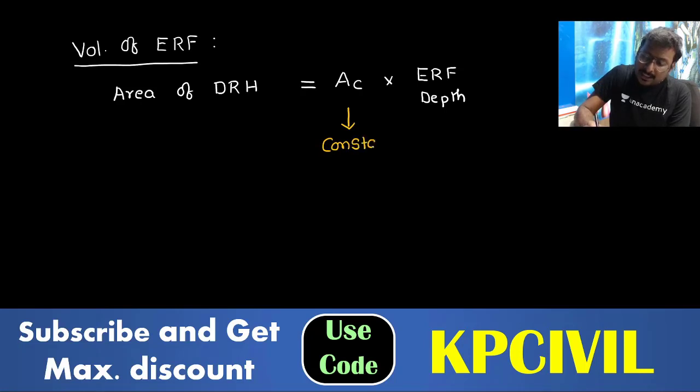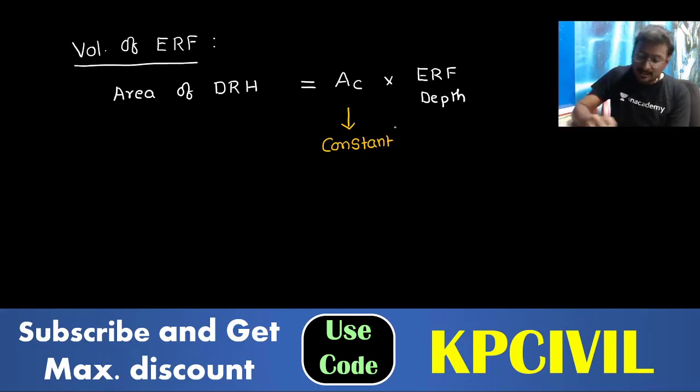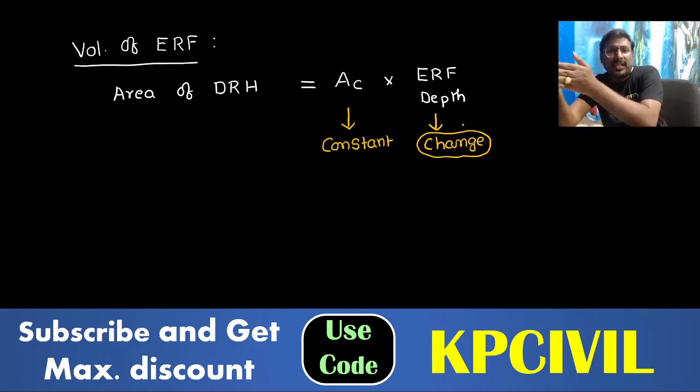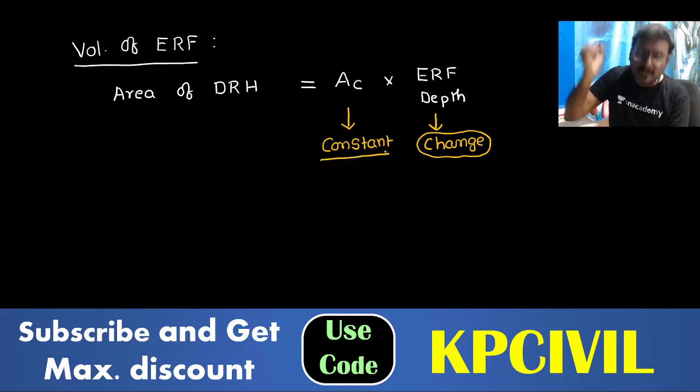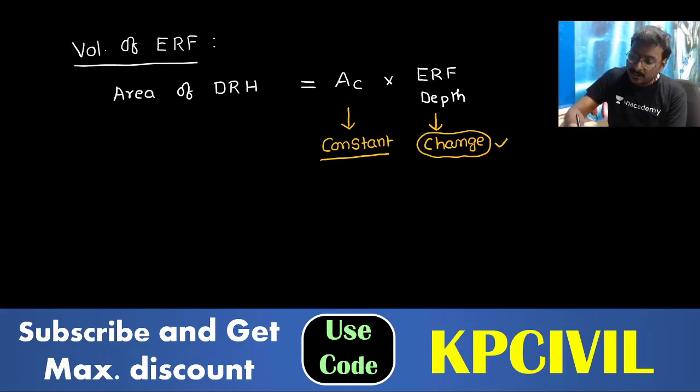Then why are the ordinates of the hydrograph changing? Why are the discharge ordinates of the hydrograph changing? So we will consider that discharge ordinates of the hydrograph change because of change in effective rainfall depth. Today, after 1 week, after 10 days, after 15 days, after 2 months, after 6 months, area of catchment is constant. What is changing? Why is the direct runoff hydrograph area changing? Because effective rainfall depth is modifying.